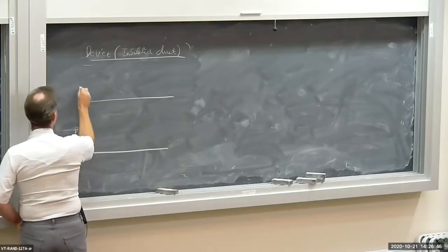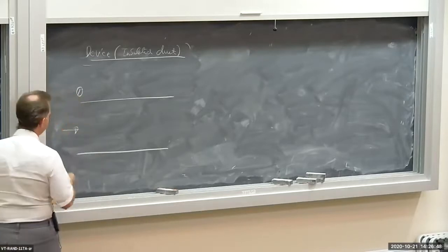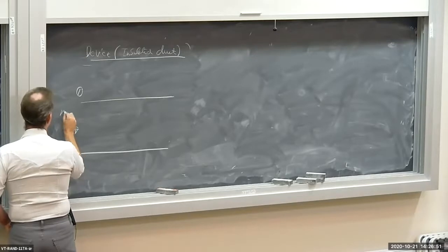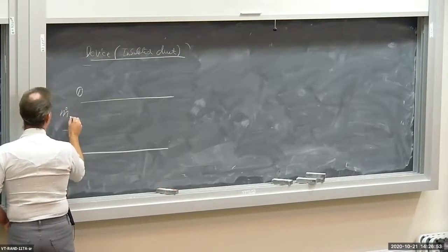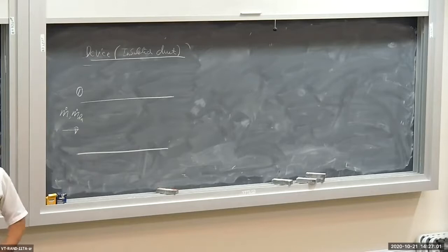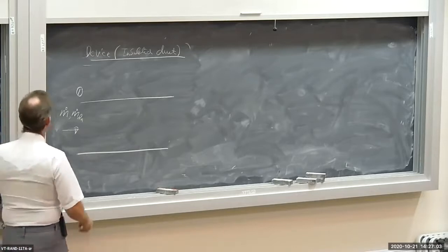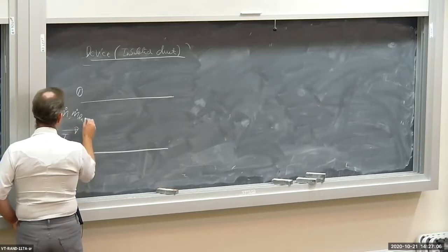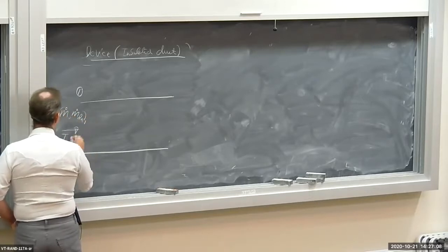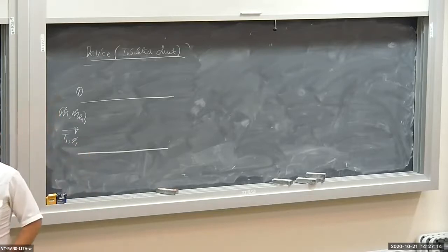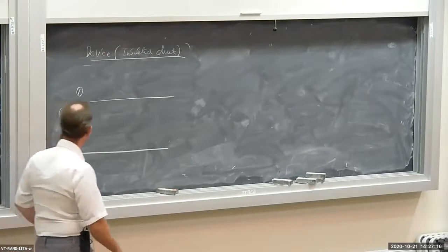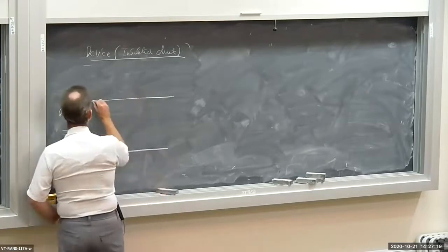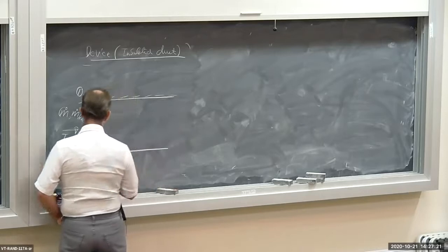Now I have an inlet at location 1, and I have air coming in. I have a certain amount of moist air coming in, and as a result, a certain amount of dry air coming in. Dry air is one component of the moist air. I have a certain temperature, and this is all at state 1. I have a certain temperature T1, and I have a certain relative humidity psi1, okay? Now this is insulated, so there's no heat transfer.